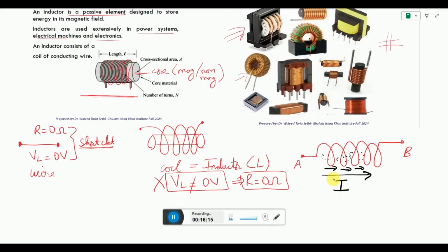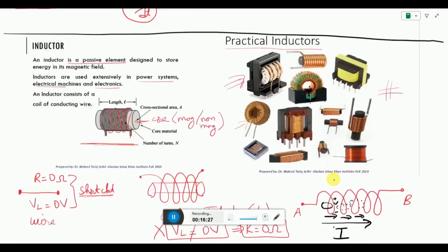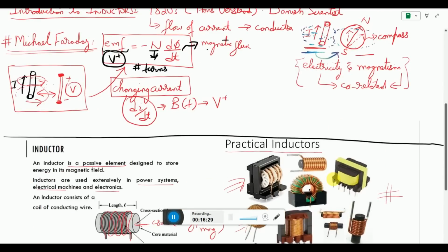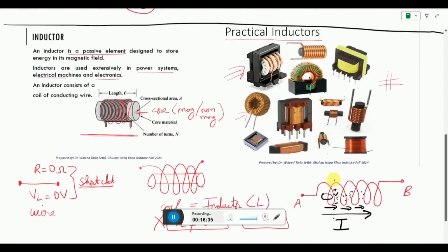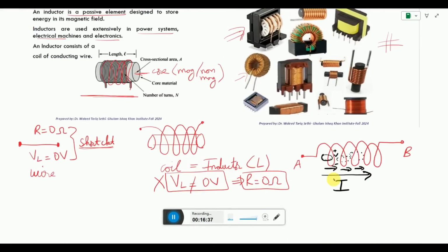Now what is happening? Since the magnetic field is produced in this coil, it is going to induce a voltage over here as well, and this process is basically the self-induction, which Faraday was explaining in his principle when he brought this wire shown in red closer to the black wire. We saw that the voltage was induced. So the same principle applies to these coils individually.